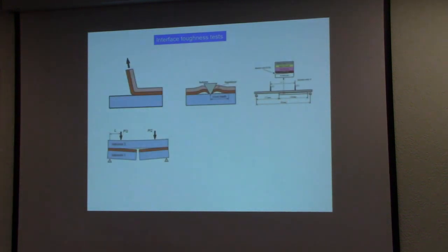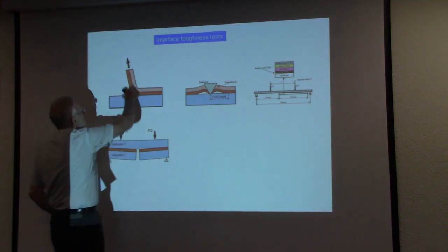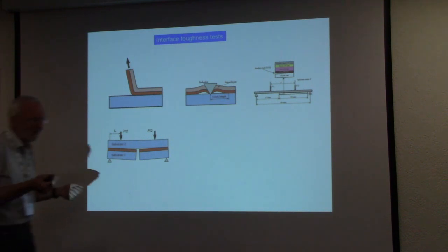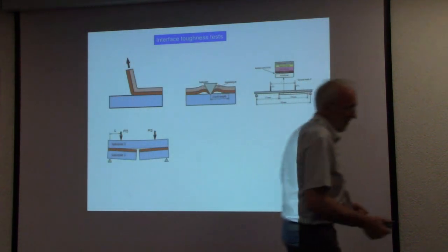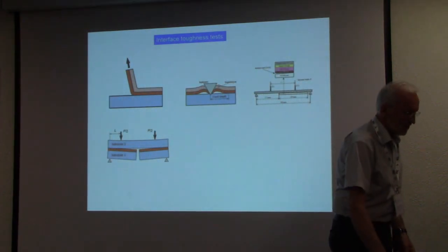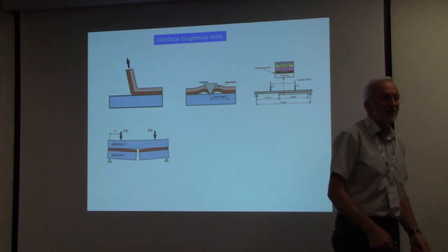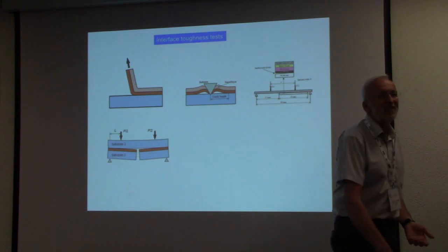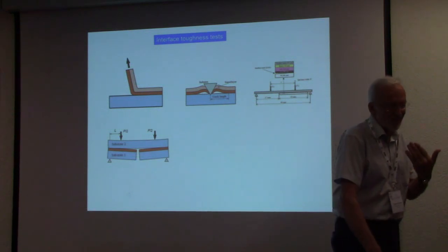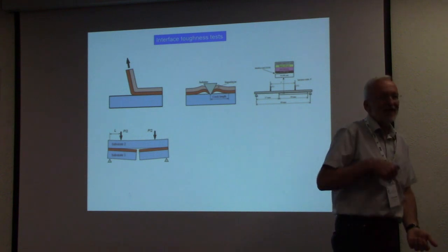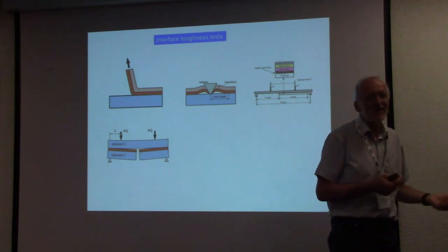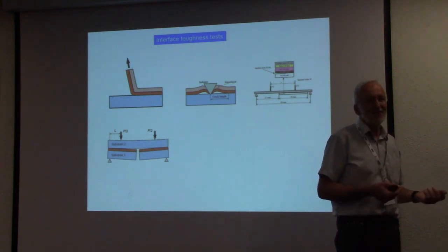Other very simple techniques are that they try to peel up the film. They are very simple techniques in industry. They take some stretches, glue it on, with glues of different strength, and then look at for which glue strength we get the peeling up of the material, and try to qualify the different types of treatments of the interface toughness.